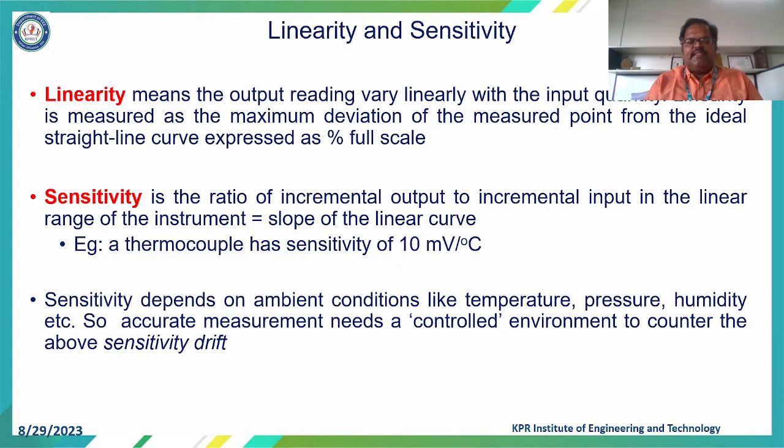Then linearity and sensitivity. Sensitivity is the ratio of the incremental output to the incremental input. It varies with respect to the input and output, and it may depend on conditions such as temperature, pressure, and humidity.